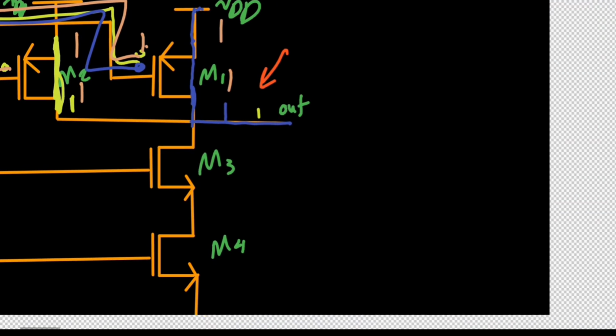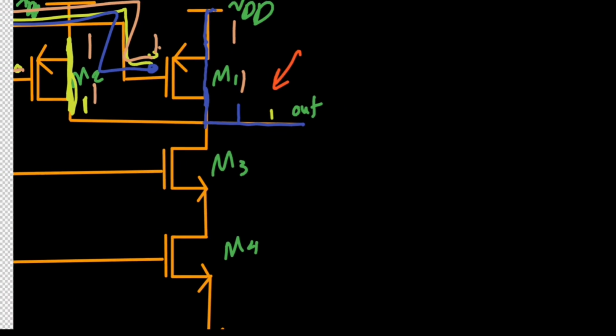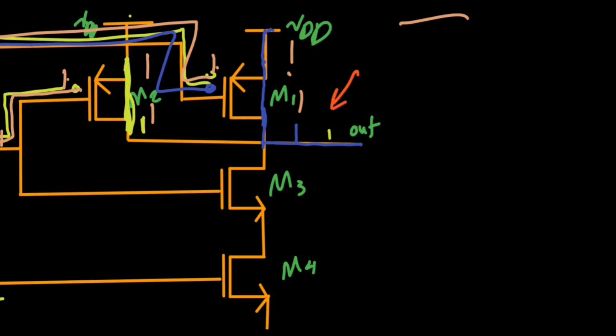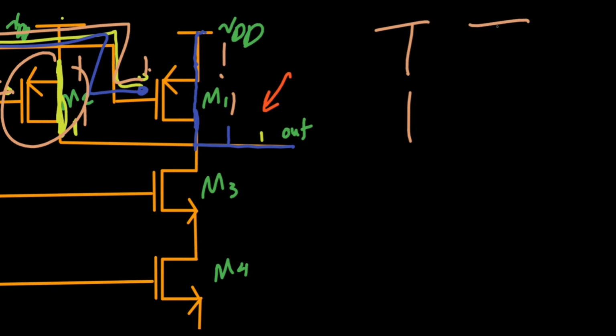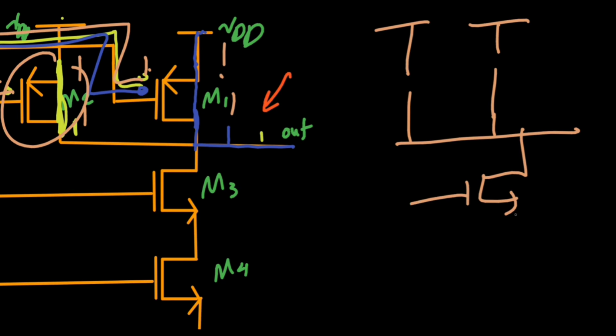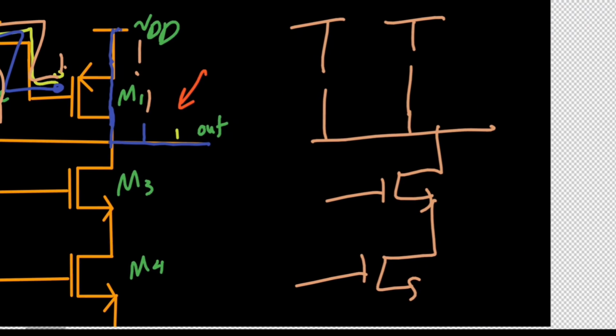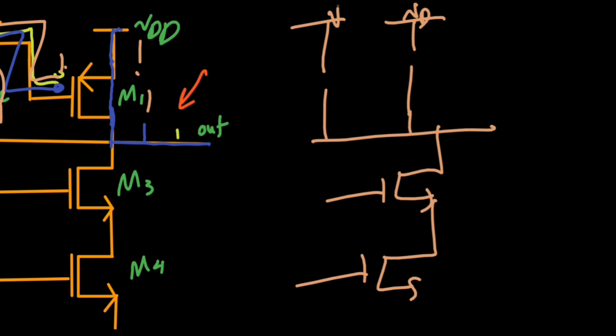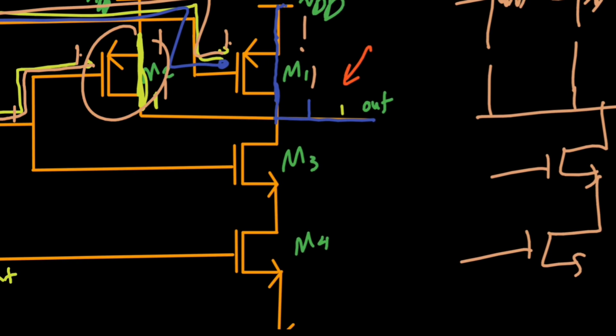If I want to simplify the circuit more to the M1 and M2, I would have something like this. This would be the M2 transistor, because it is off, and this would be the M1. So I also have these two transistors which we haven't checked yet. This is VDD, this is VDD, because they are just disconnected from the out wire. They wouldn't have any effect on that.